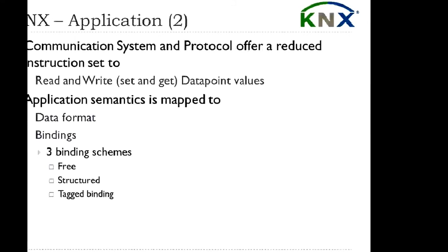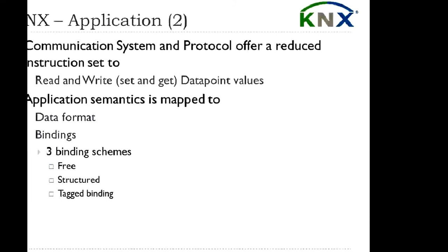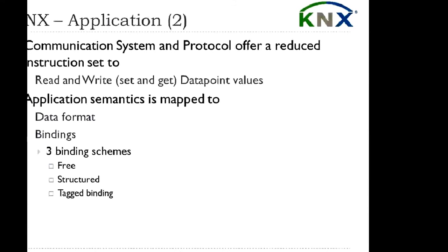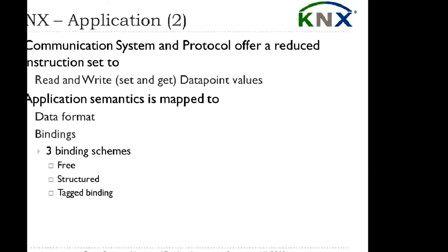So how can devices communicate? Basically, they read and write data points. One device reads a data point from the other and takes some action, or writes a data point on another device requiring some action. For example, if I want to switch on the lamp, I will write the switch data point on the lamp actuator, and I will put, for example, a 1 value inside that data point. That means that the actuator software reads 1 and switches the real relay to which the lamp is attached.